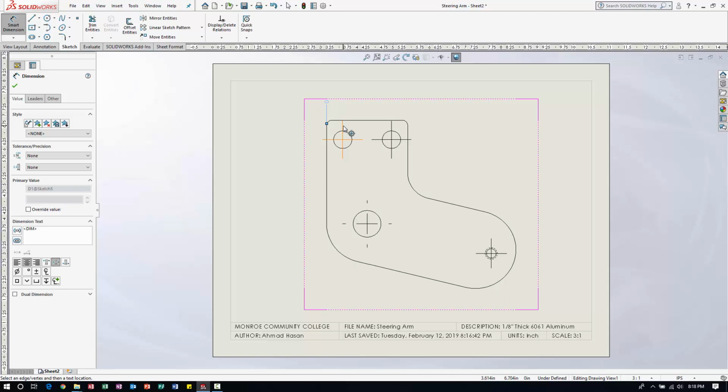And let's start dimensioning these positions for the holes. Again, I'm just adding dimensions to that drawing. So this location, this is my 0, 0, it's 0.15 inches away. I also want to add this point. Again, I'm just going to replicate the drawing I've created.